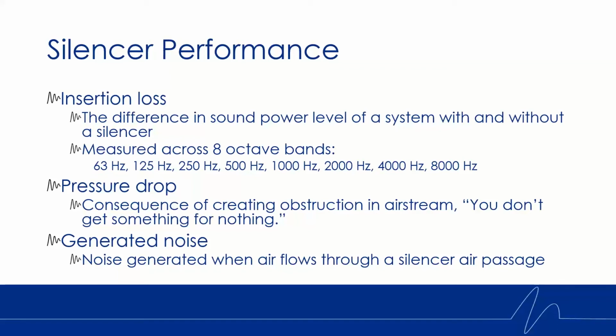Now, this is the consequence of putting a silencer in the system. The silencer creates an obstruction. You're going to get a little bit of turbulence. You're going to get some pressure drop associated with putting the silencer in.